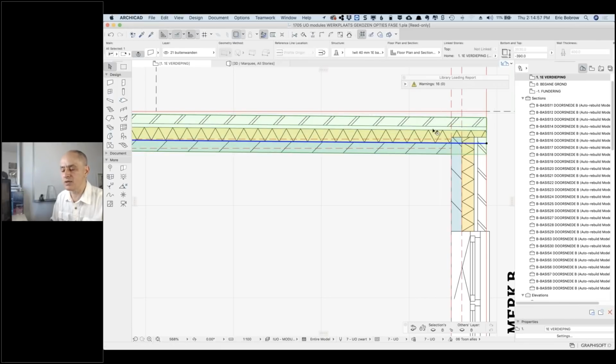Now, if these were straight and they weren't cleaning up, it would make sense to force them to clean up by telling it to find the natural ends by using the intersect. So when I say use the intersect, now we get a clean result. Of course, this is still not square.